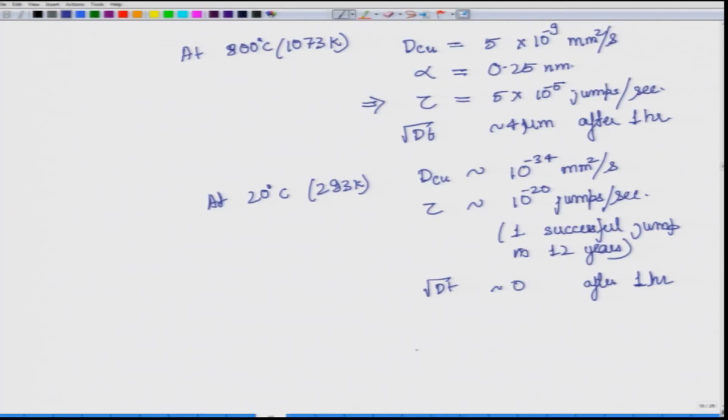So, this is the one aspect of substitutional diffusion, which is the diffusion of the same species, also called as self diffusion. Next, what we can look at, inside the material, even in a pure material, you will have the material and also the vacancy. Now, if the atoms are moving, so can the vacancies move. So, we can also talk about vacancy diffusion.